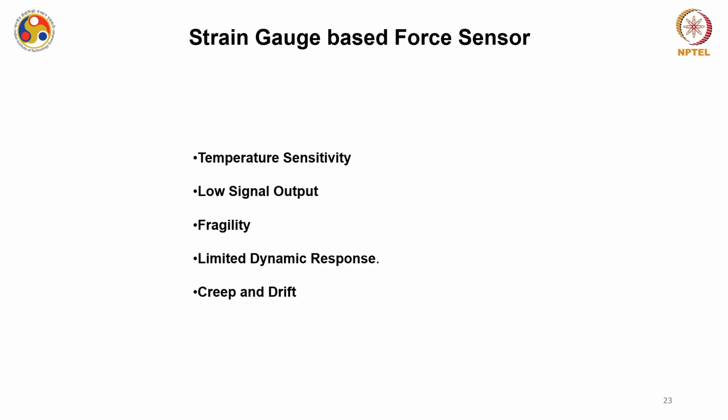The signal output of a strain gauge is usually low, and you may require a special kind of amplifier to amplify the signal. The devices are mostly fragile, so you have to handle them with care. The dynamic response of strain gauges is mostly limited.